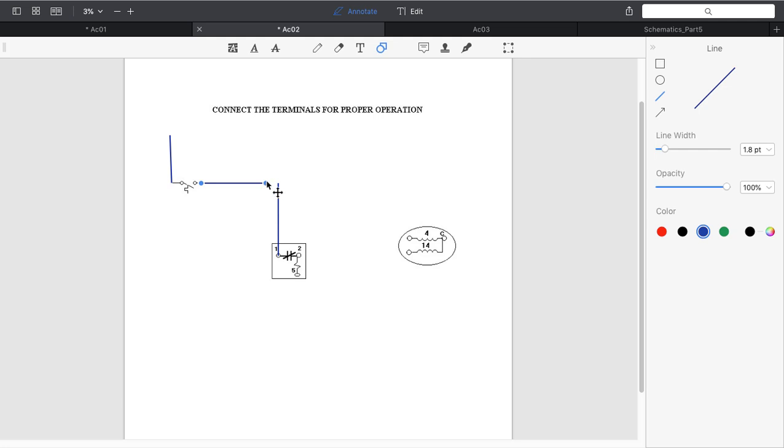Now, if this had a start capacitor in the way, I would be putting it in here someplace, but it doesn't. Pin 2 goes to my start winding. Pin 5 comes over here to common. And then I'll bring in a neutral. Actually, we'll just call this neutral, or line 2, as well.